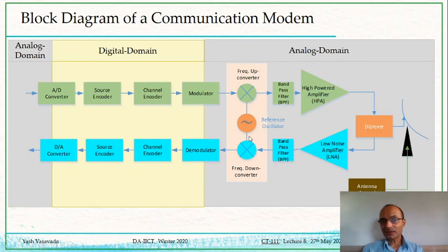At the receiver side, we need those cosines and sines not for transmission purpose but for demodulation purpose. This demodulator, we want it to operate at 0 hertz. We don't want it to operate at such a high frequency of f of c, which can be, as I said, in some multiples of gigahertz.